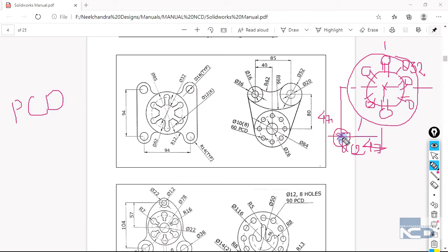Similarly, once we have created this one piece, we are going to mirror it on the other side like this, and once we have these two pieces we are going to mirror them on the opposite side like this. So now we have all four circles over here. Similarly, we are going to create this concentric circle as well, and this time it will have a radius of 14 mm. Here again we are going to create all four circles like this, and we are going to join them with the help of lines like this.